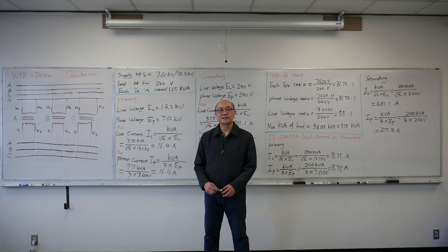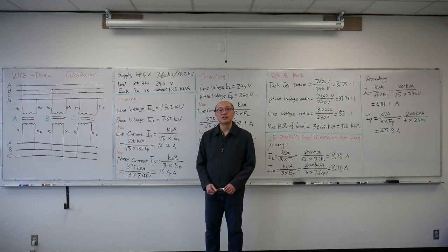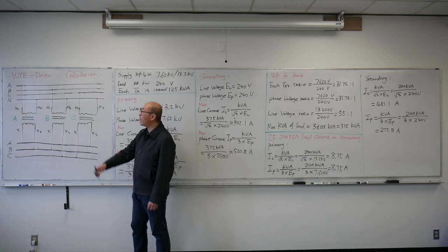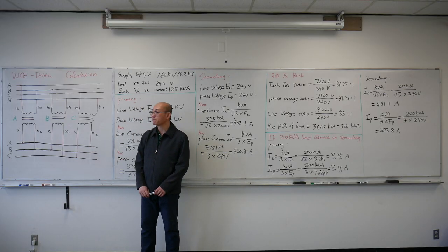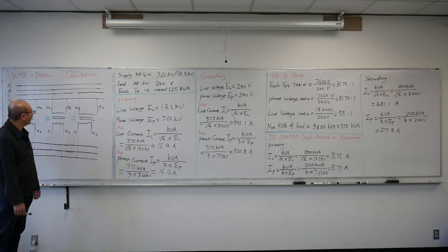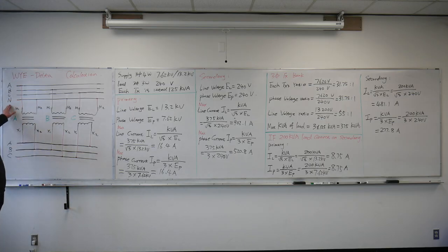Hello everyone, in this lesson we're going to talk about Y-delta three-phase transformer calculation. So here's the connection for a Y-delta three-phase transformer. The primary, the high voltage side, is connected in Y, so I have a neutral conductor down here. The secondary is connected in delta.